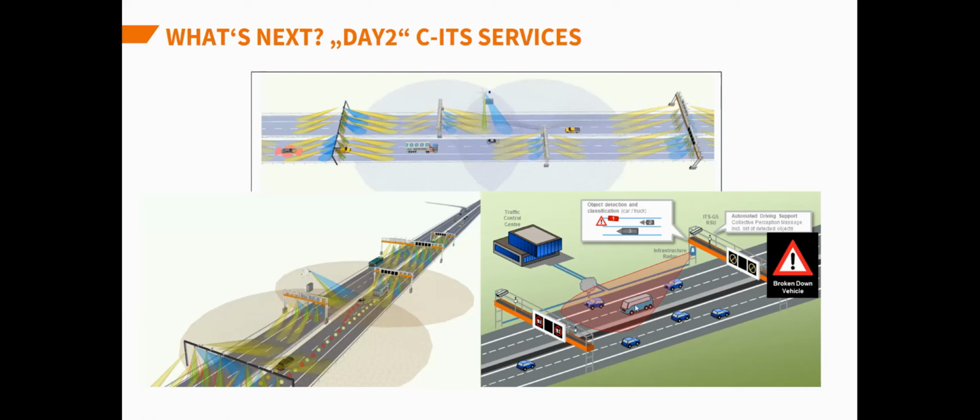Something that we did not have on the slide with the 4 messages before, but you can encode objects and their position and their heading, basically an object list, into a message, and broaden the electronic horizon of a vehicle via this bird view that I've shown at the beginning of my keynote speech.